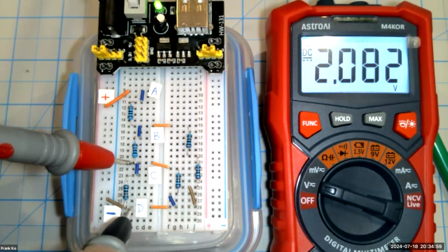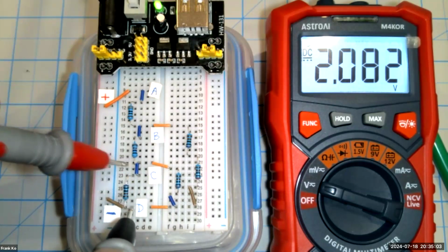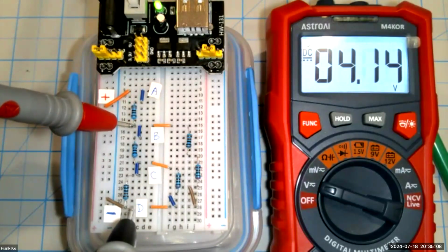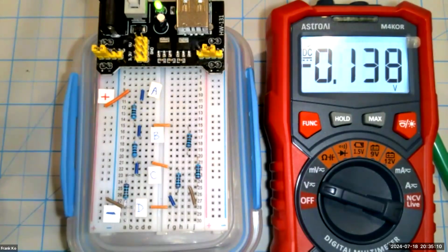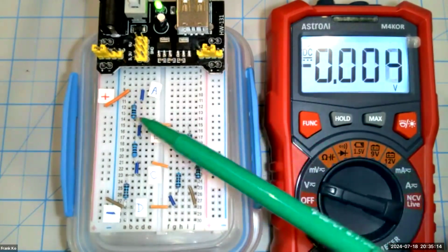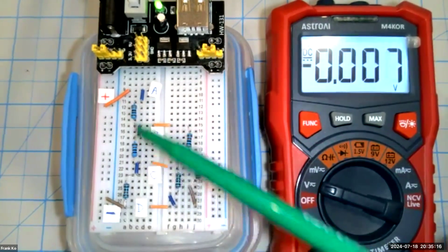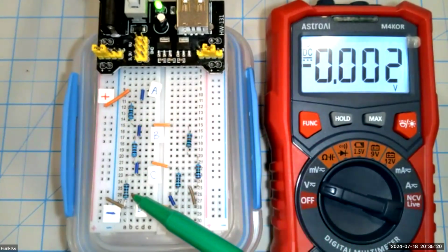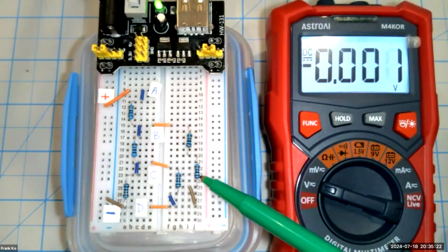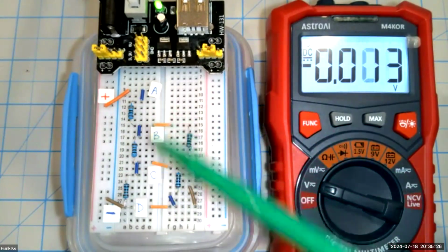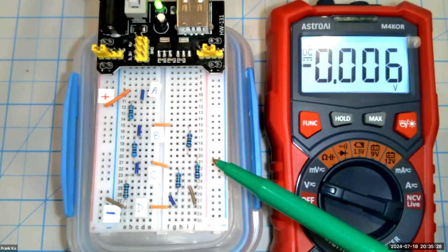Look at that. We needed 2 volts at point C. We now have 2 volts at point C. We needed 4 volts at point B. We have 4 volts at point B. Voila. So now by recalculating the new values of R1 and R2, inserting them in here, we now have a voltage divider on this side that is now loaded. So this is called a loaded voltage divider that meets all of the circuit parameters.